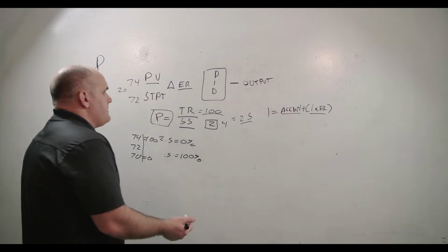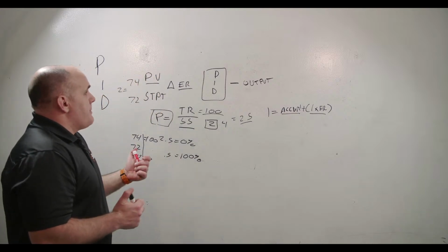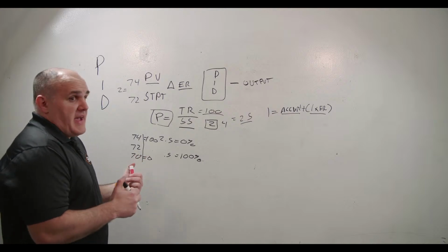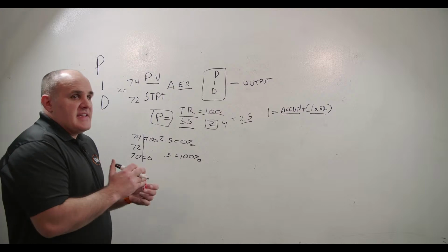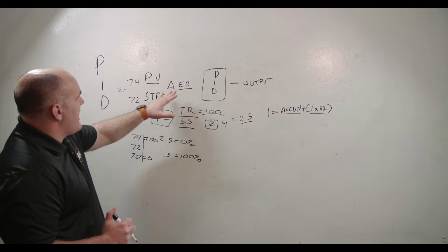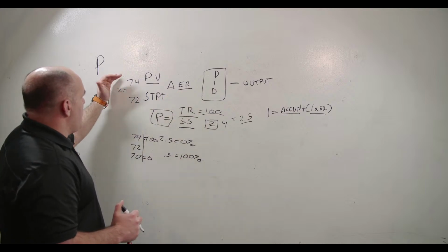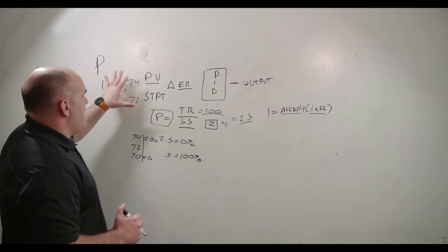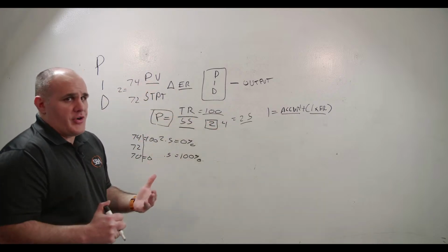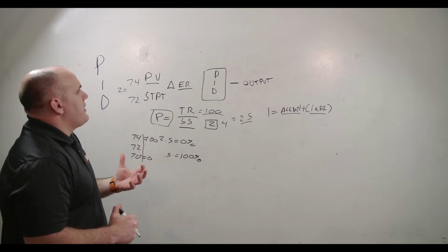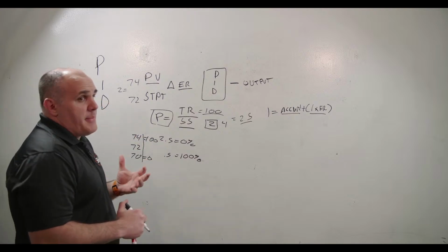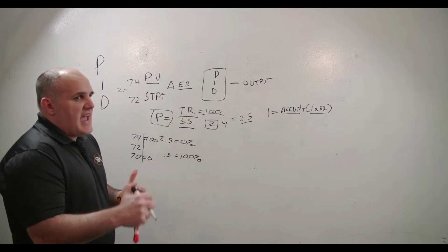So why do we do that? The reason we do that is a proportional response can sometimes get stuck. You can have a load in a space where, with this error, we've got a 2-degree error, let's say, we're at 50%, 2 times 25, and we're just not overcoming that load. People are like, we're just not able to achieve it and we're stuck, and that happens quite a bit in zone temps. It doesn't happen so much in pressure.